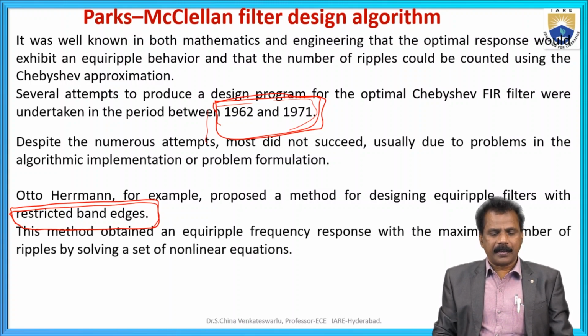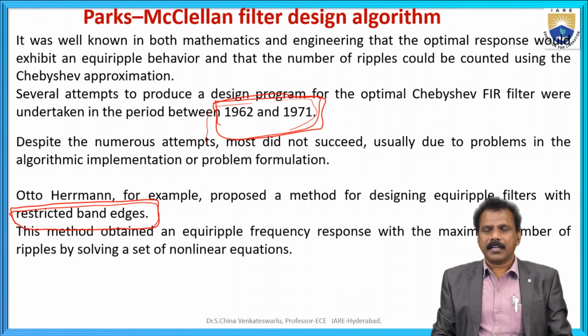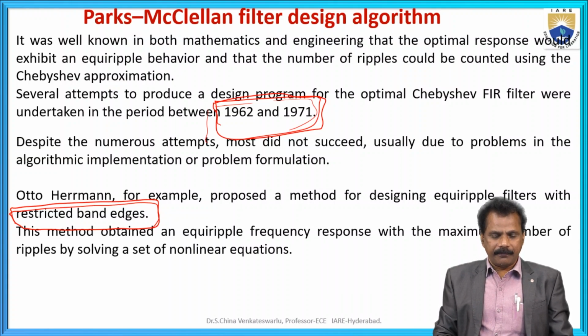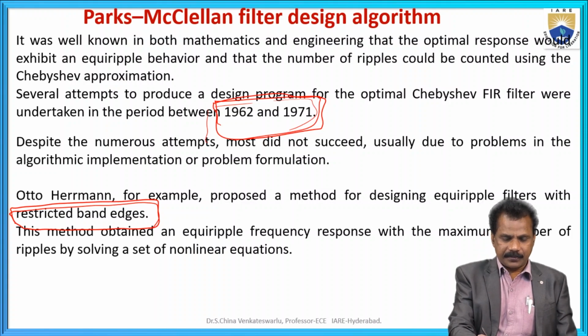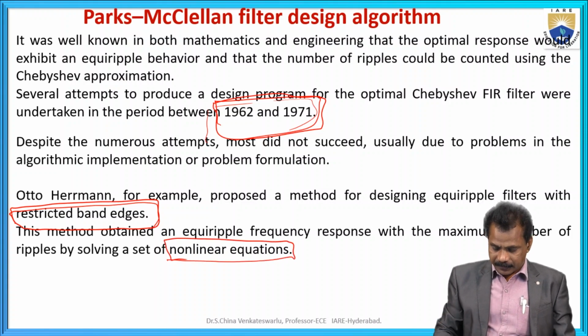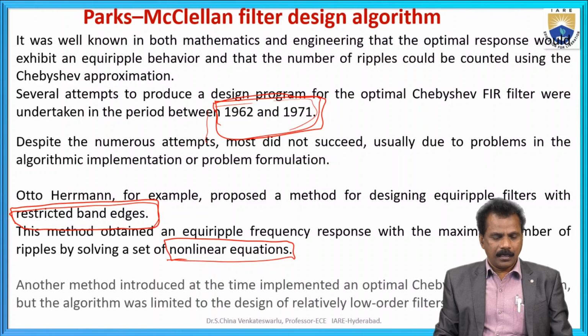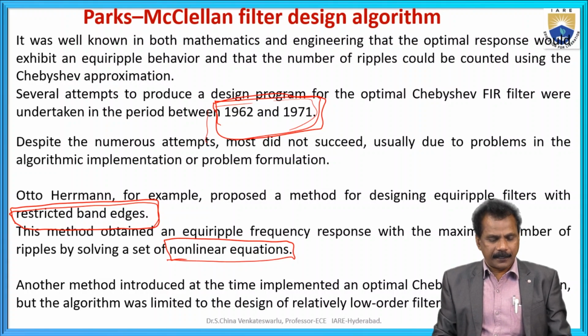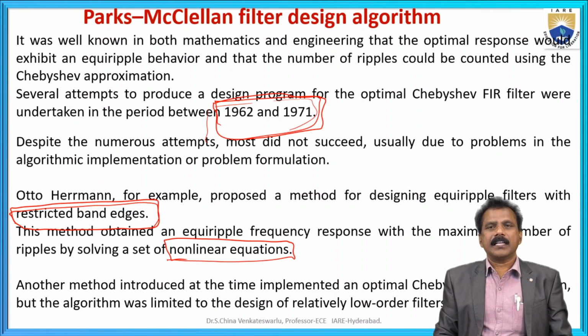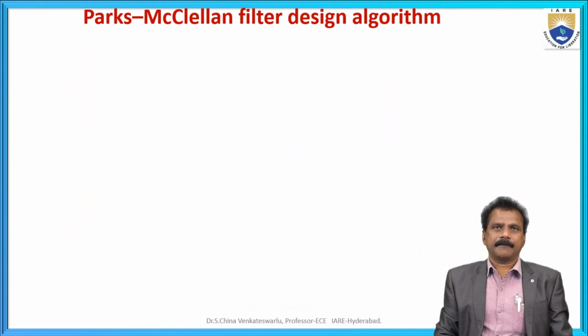This method obtained an equiripple frequency response with the maximum number of ripples by solving a set of nonlinear equations. Another method implemented an optimal Chebyshev approximation, but the algorithm was limited to the design of relatively low order filters.